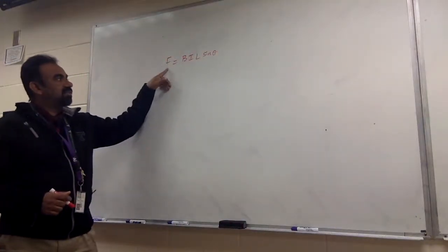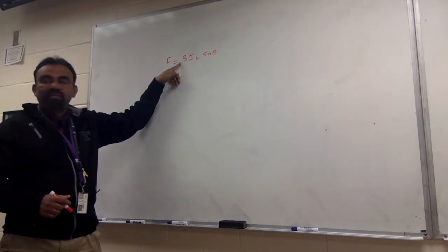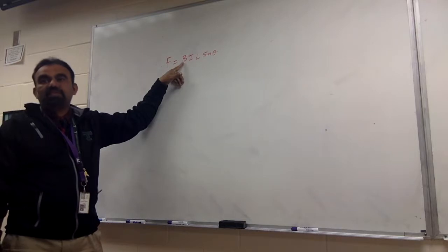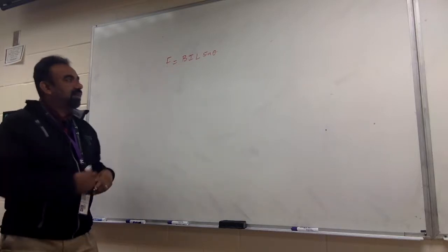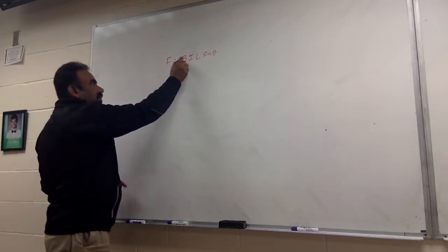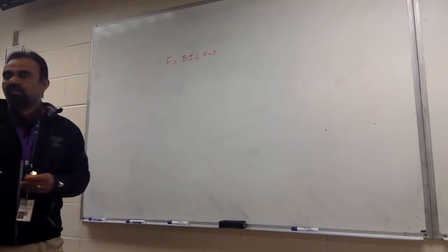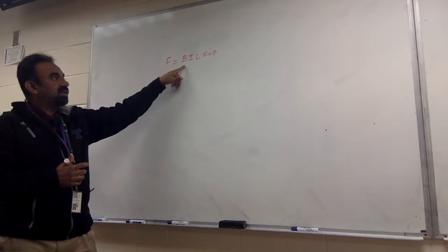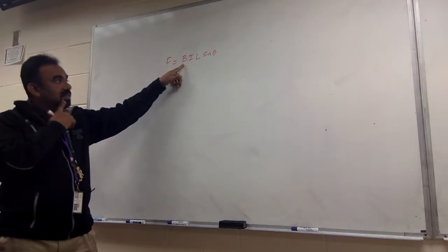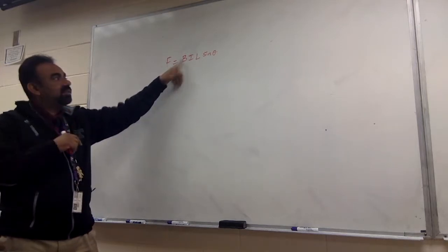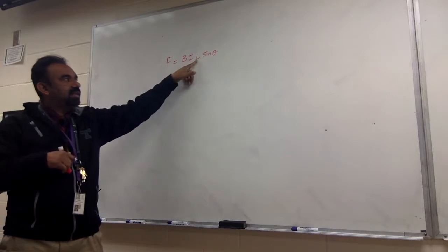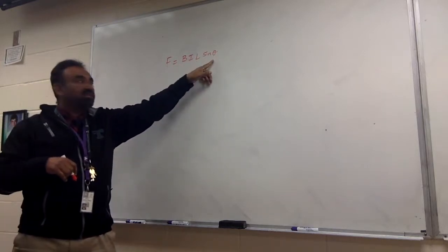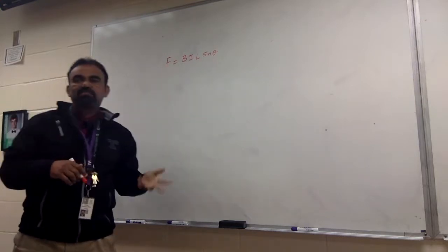The actual equation is F equals K B I L sine theta. K takes value 1 through the definition of the Tesla. So the magnetic field, or the magnetic flux density, which is also another term that is used, is to be measured in Tesla, current in amperes, length in meters, and when the angle is 90 degrees, then you can get the maximum force coming out of it.